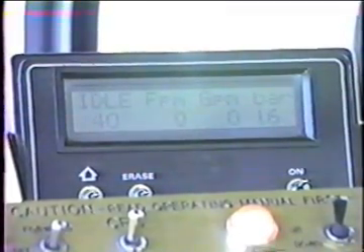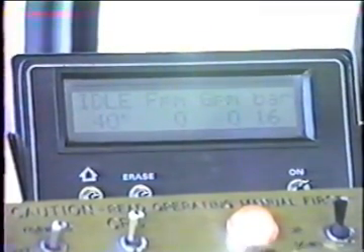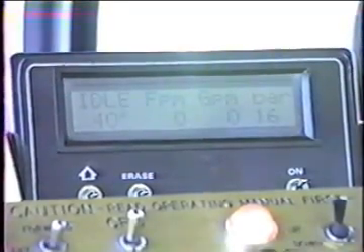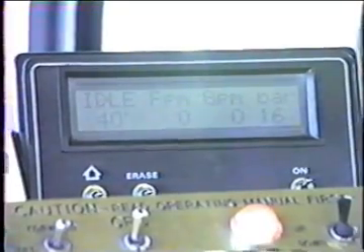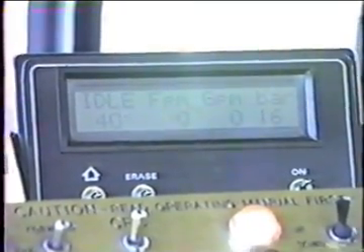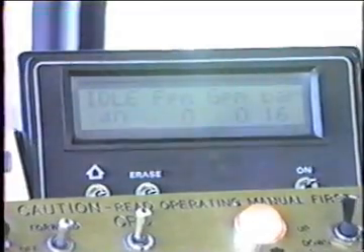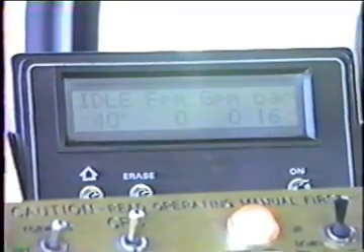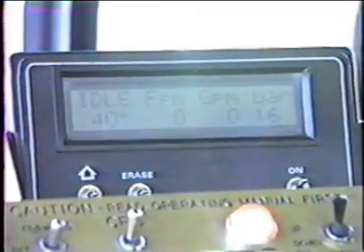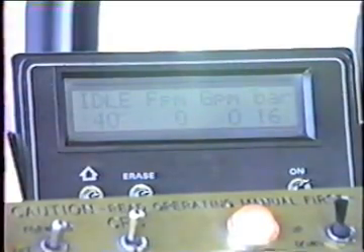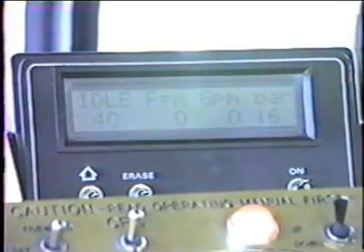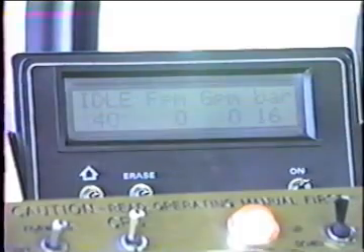Okay, and as soon as we turn that computer on, it'll tell the asphalt pump to do just that. That is, it will start turning the asphalt pump and it'll turn it at 40 gallons a minute. Idle speed, circulate speed, that's the same thing. And any time that the master switch is in the off position, the computer will be in the idle mode. It knows that any time we're not spraying with the spray bar, it should circulate the spray bar, and it'll circulate it at whatever that idle number is.